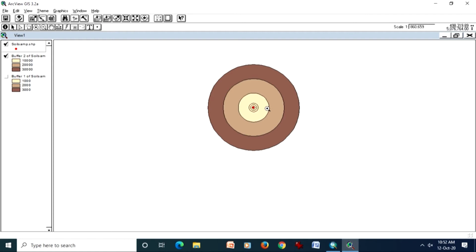So in order to have more softer and realistic boundaries, what we can do is first create a surface using interpolation techniques, create the buffers, and for the buffers we can extract from the background layer, that is the interpolated layer, and we can get very smooth circles, multiple circles showing the conditions which might be or would be there. So it depends on which application you are trying. Then as per that and depending on distance, these circles or buffers can be created.